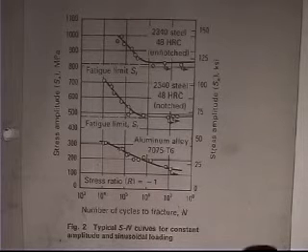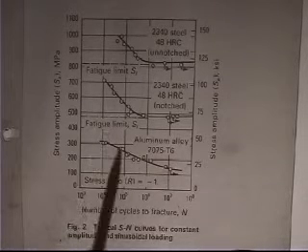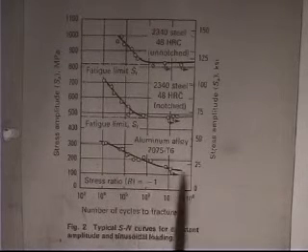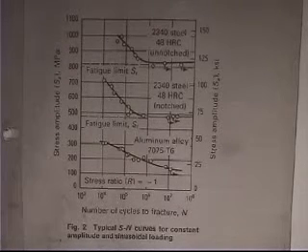If you go to aluminum alloys, you notice this aluminum alloy doesn't flatten out. They're still drawing it with a little slope. It doesn't have the fatigue limit. So that's how we measure fatigue in the laboratory now. And you can go to these plots and you can predict the life of things. In a second, we're going to go through, let me show you one more plot.